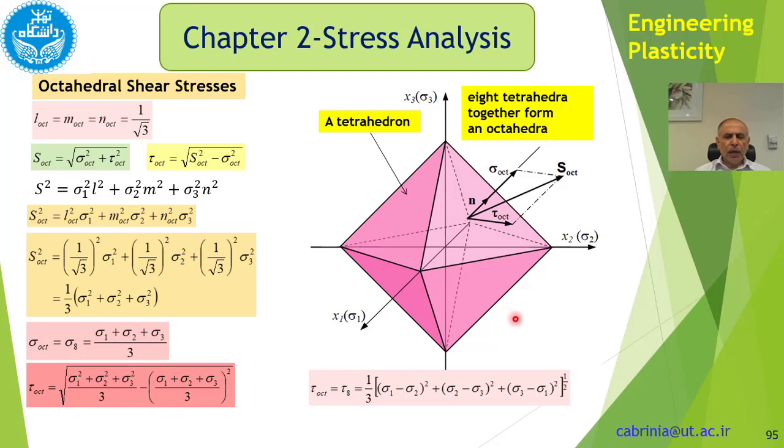Now, you will notice that this shear stress is the one which is responsible for the slip, and it's responsible for the deformation. Later on, you will see that in the yield criteria we use this relationship.